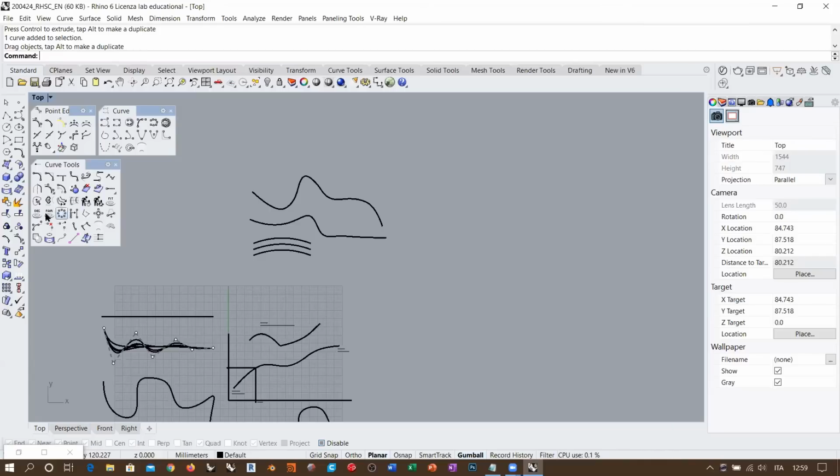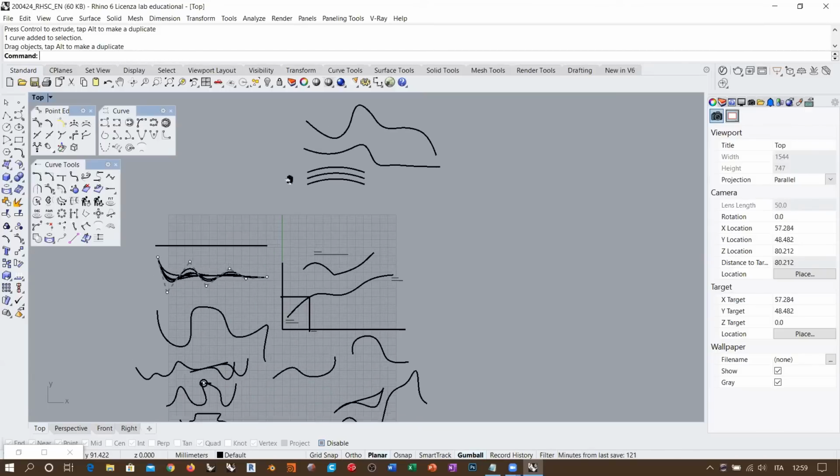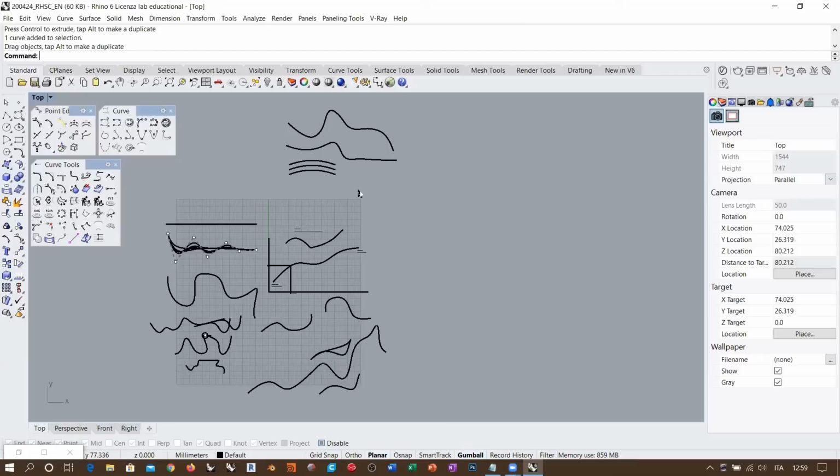But this is something that we are not going to discuss, because these are very problematic commands. If you find yourself using the fair commands, it means that you did something wrong before using it, okay? So I do prefer to have a linear approach to topological control in order to create directly the desired topology and the desired shape of the curves, okay?